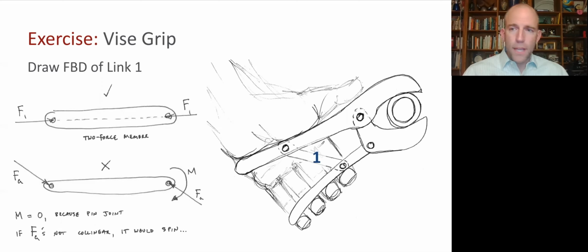And if we only have two forces left, then it has to be a two-force member where they point right at each other. They're collinear, equal and opposite. And we know that because if they didn't point at each other, then if you do moment balance about this point, this force has a lever arm, right? It will cause that thing to spin. And then you would need a reaction moment. And we've assumed that there are no reaction moments.